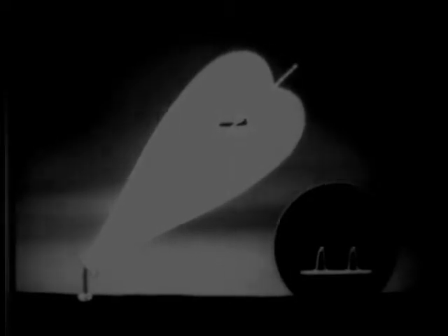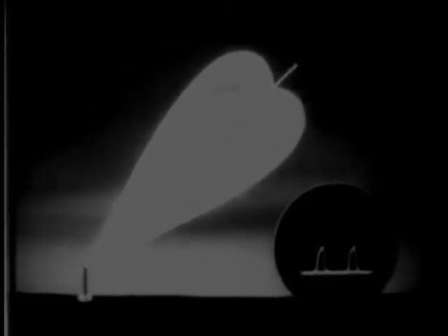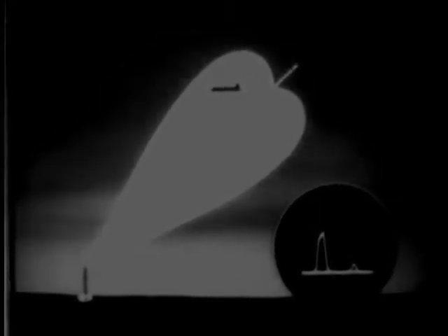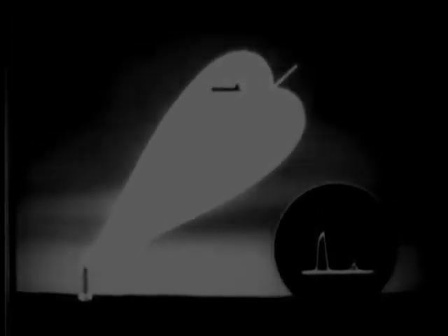When the target's centered in the lobes, the pips on the elevation scope are balanced and your angular height data is correct. If the plane gains altitude, naturally it'll be in a stronger part of the upper lobe, a weaker part of the lower one. So one pip grows, the other shrinks.